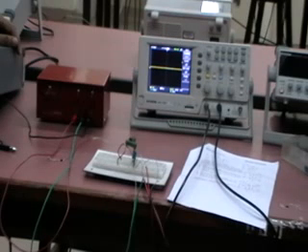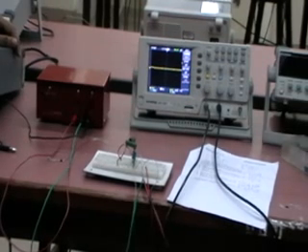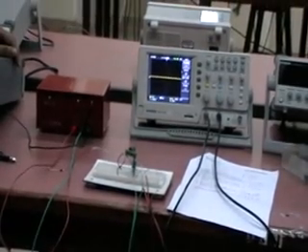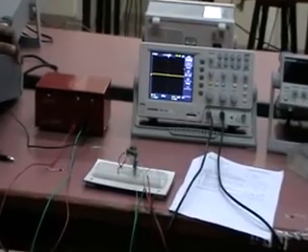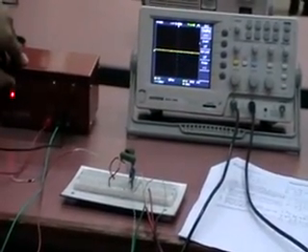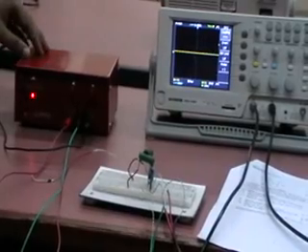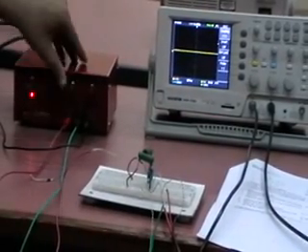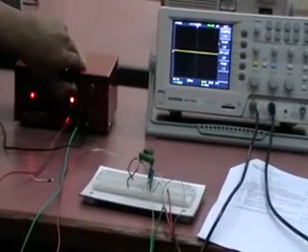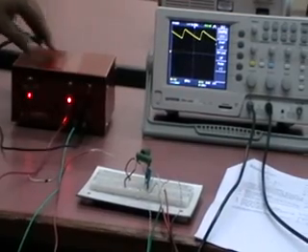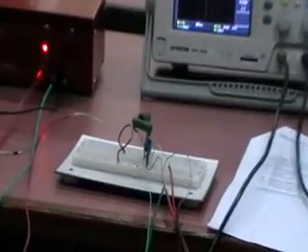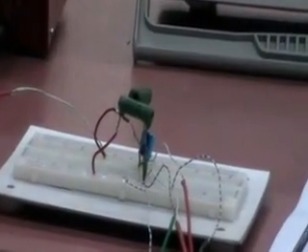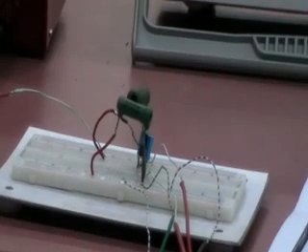So, coming to the rectified part with capacitive filter, in this section we will study the effect of capacitive filters on ripple voltage and peak diode current. The 1 ohm resistor in the following circuits is used to observe the diode current waveforms, by using one channel of the DSO to observe the output voltage and the other channel to observe the diode current simultaneously, channel 1 and channel 2. The circuit connection is done according to the diagram given in the manual.